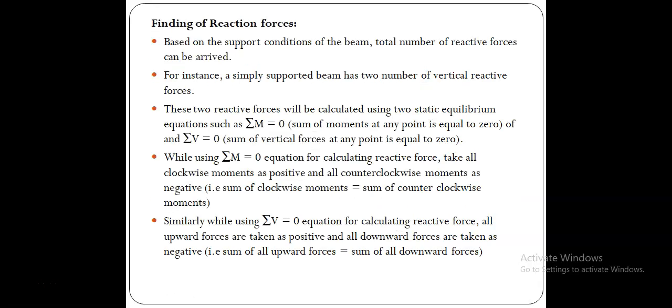Then how can we find the reaction forces? Before analyzing any beam, if we want to find the shear force and bending moment on the beam, we must find the reaction forces. Only by knowing the reaction forces can we calculate the shear forces and bending moment along the spans of the beam. Based on the support condition of the beam, first we have to determine the total number of reactive forces.